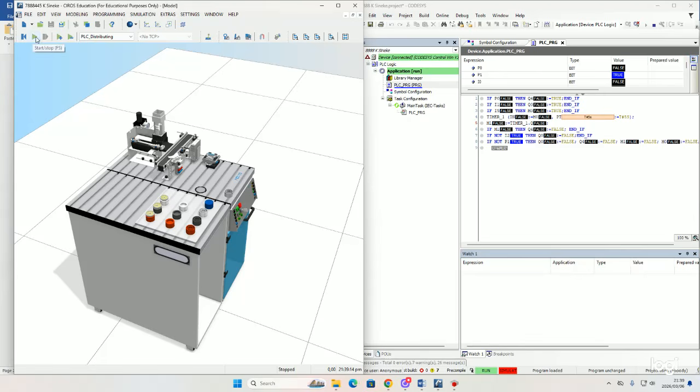Okay, let me stop, restart, play. Then our cylinder should take 5 seconds to retract. There we go. So yes, indeed, our Codesys doesn't count down, but at least it's visible that the actuating cylinder indeed executed, or memorized, the 5-second delay.